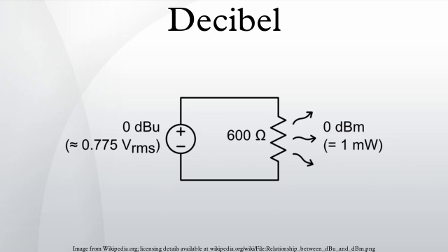The decibel symbol is often qualified with a suffix that indicates which reference quantity has been used or some other property of the quantity being measured. For example, dBm indicates a reference level of 1 mW, while dBu is referenced to approximately 0.775 volts RMS. The definitions of the decibel and bel use base 10 logarithms. The neper, an alternative logarithmic ratio unit sometimes used, uses the natural logarithm.